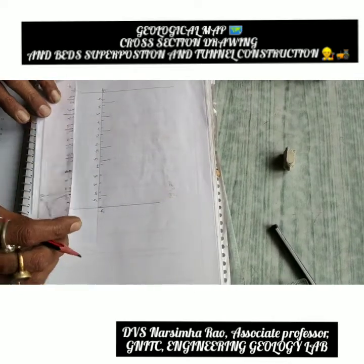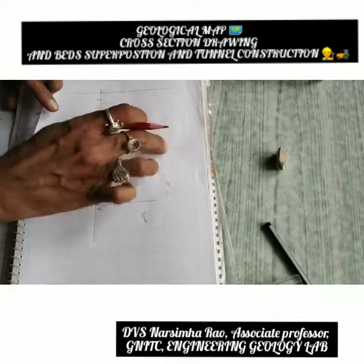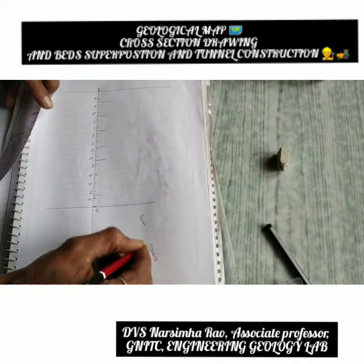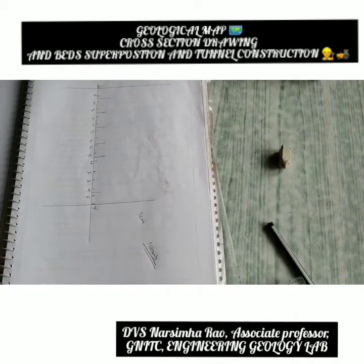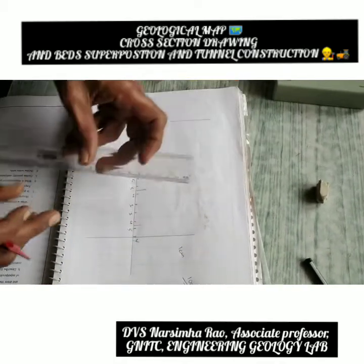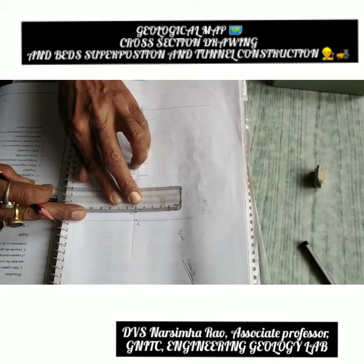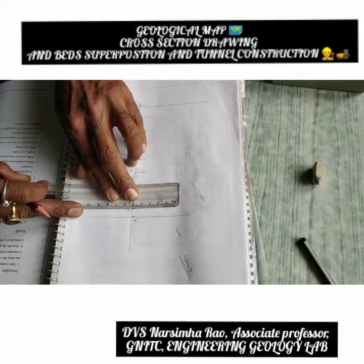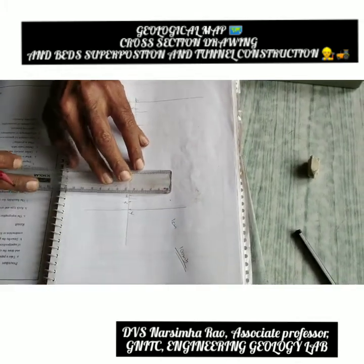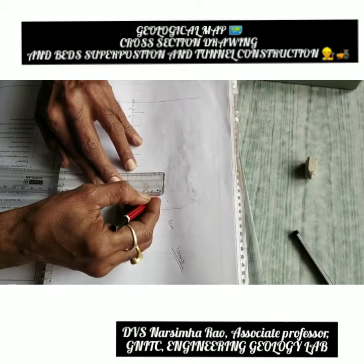Okay. Now take the scale. See, 1 centimeter on the paper equals 100 meters on the ground. This is the scale actually given. So now take the scale. Now up to 5 centimeter, draw one line. From here, take the scale, you have drawn 5, so this is the 500 contour, so you keep one dot here. Then again you are taking 400, so keep one dot here.